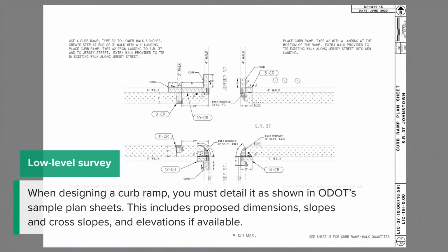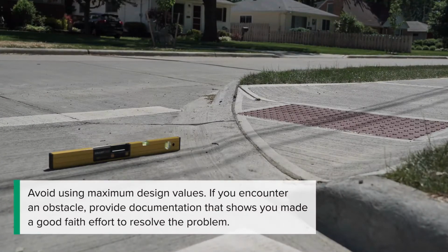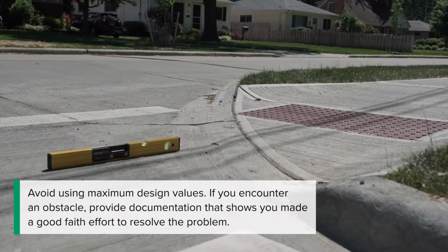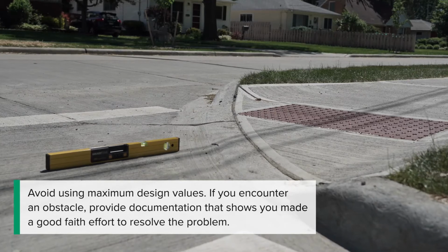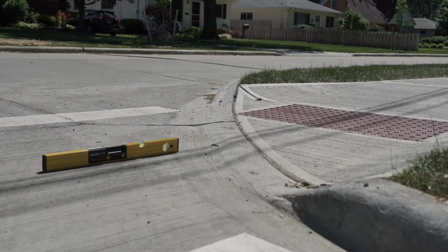When designing a curb ramp, you must detail it as shown in ODOT sample plan sheets. This includes proposed dimensions, slopes and cross slopes, and elevations if available. Avoid using maximum design values. If you encounter an obstacle, provide documentation that shows you made a good faith effort to resolve the problem.